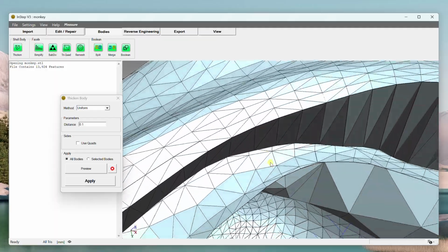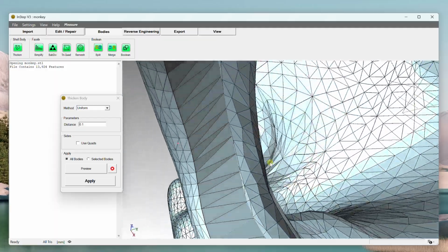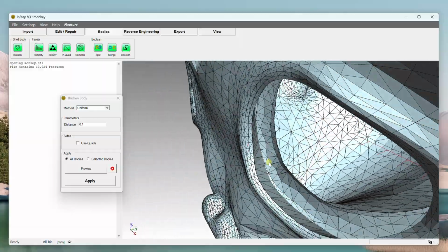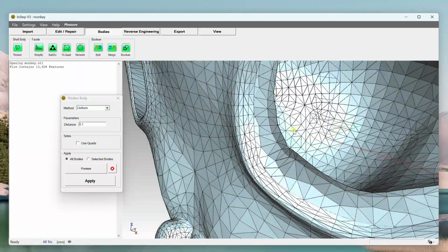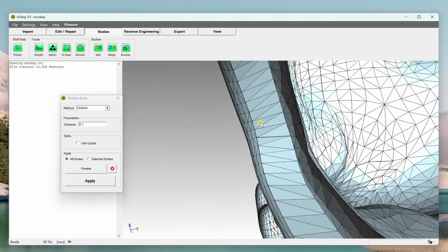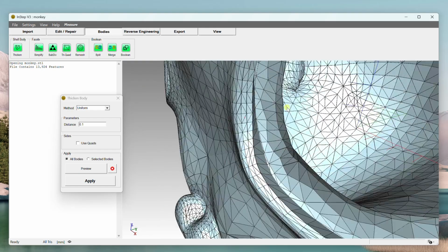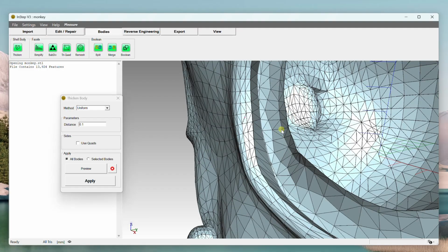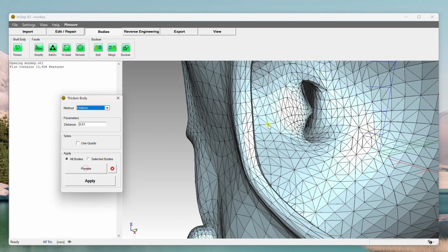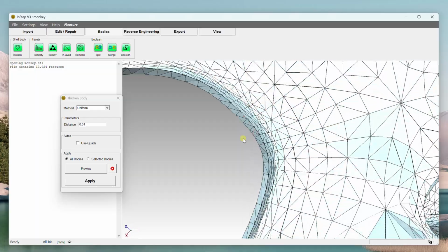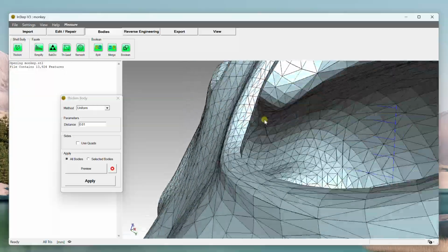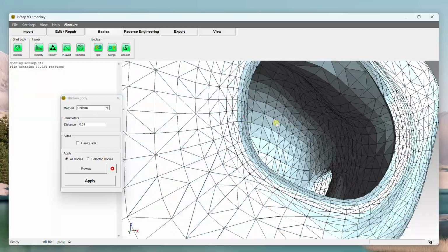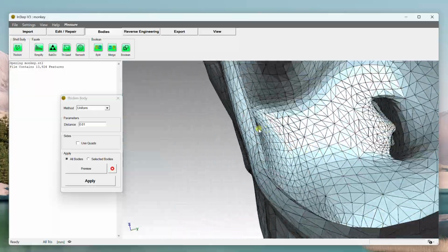we can see that 0.1 is actually too far. With an offset of 0.1 for this size model, and it is set to being a very small model, the distance is too far and the facets don't properly align anymore. So for this we may have to go a lot smaller. At this level you can actually see that the offset is uniform in thickness and small enough to still prevent collapses in probably most of the locations.